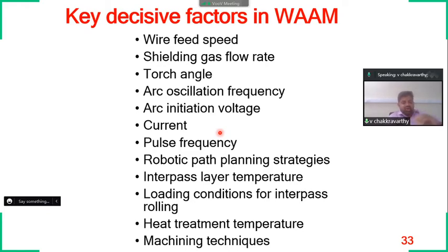First layer I have laid. I will be waiting until the deposited layer solidifies and reaches an ambient temperature like 300 degrees Celsius or 250 degrees Celsius. Until then I will wait. And once it has reached the desired temperature, then only I will lay the subsequent layer. Again, I will be waiting until the previously deposited layer reaches the same interpass layer temperature, and then I will